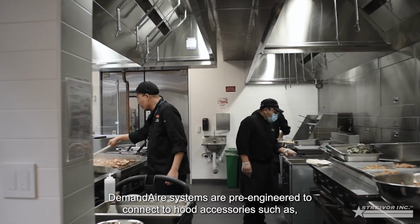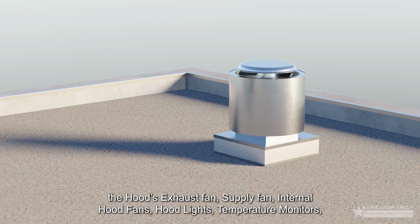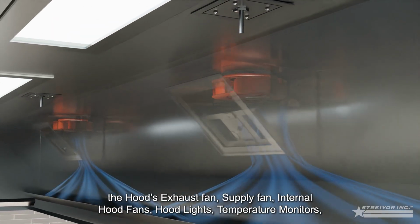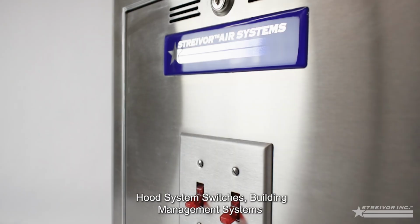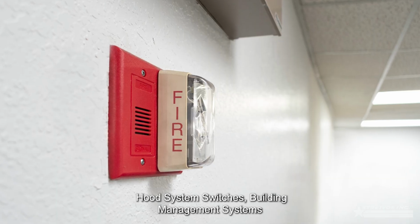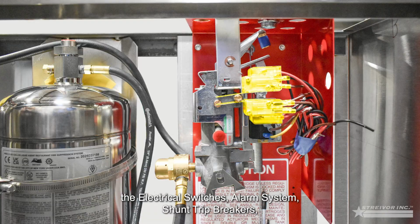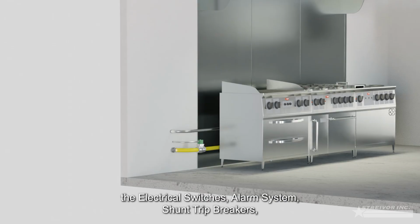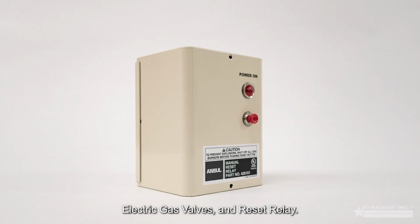DemandAire systems are pre-engineered to connect to hood accessories such as the hood's exhaust fan, supply fan, internal hood fans, hood lights, temperature switches, hood system switches, building management systems, and also the fire suppression system accessories, such as the electrical switches, alarm system, shunt trip breakers, electric gas valves, and reset relay.